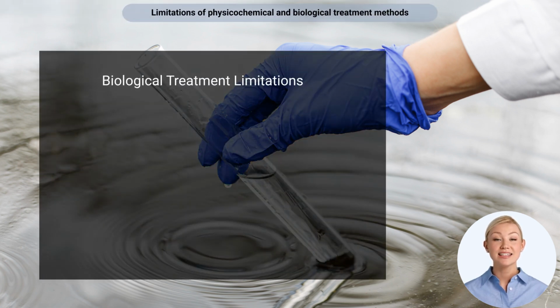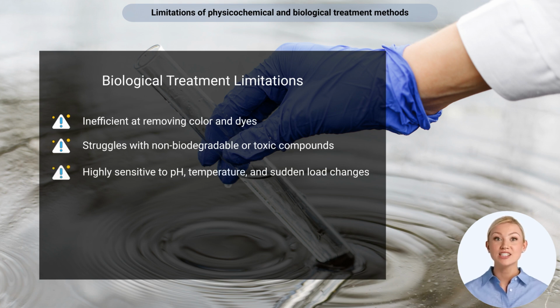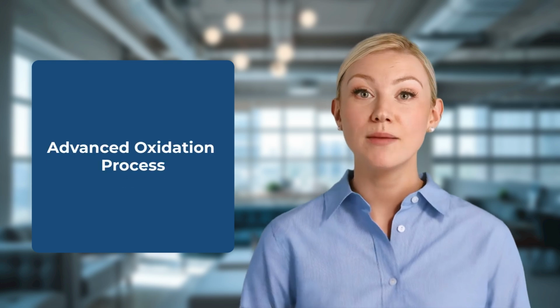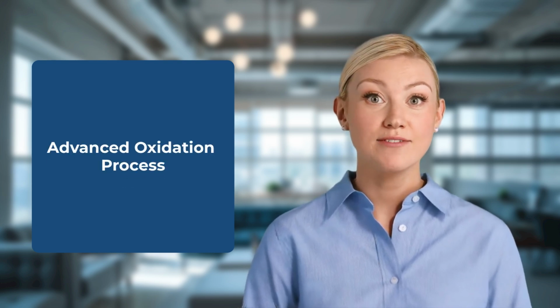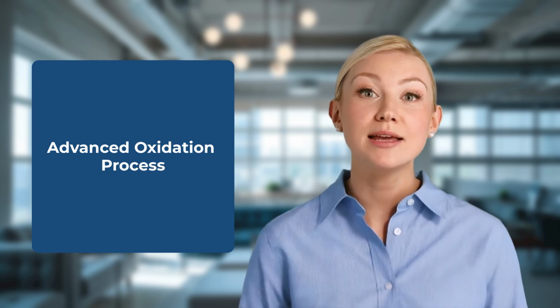Though crucial for breaking down organic matter, biological treatment has its limits. Inefficient at removing color and dyes. Struggles with non-biodegradable or toxic compounds. Highly sensitive to pH, temperature, and sudden load changes. Demands long retention time and large space. Produces biological sludge needing further treatment. Hence, some advanced oxidation processes, like Fenton oxidation, are required for meeting discharge standards or enabling water reuse.